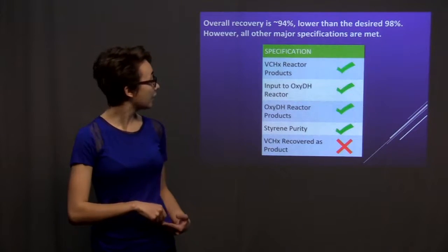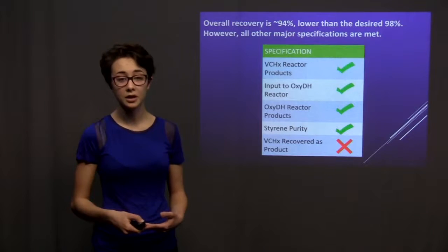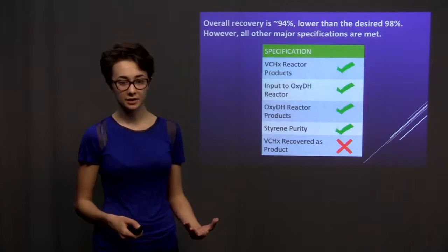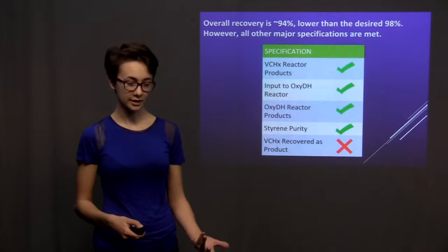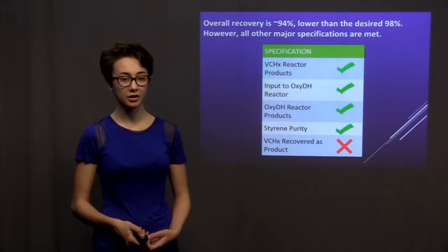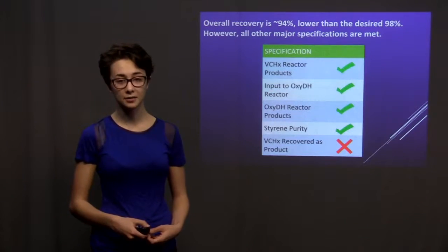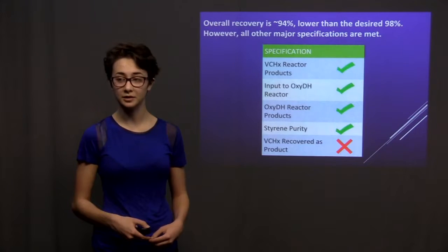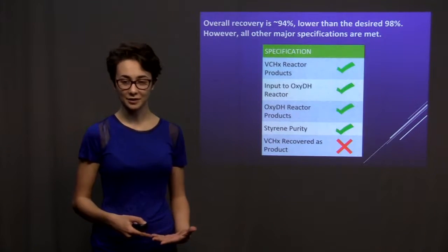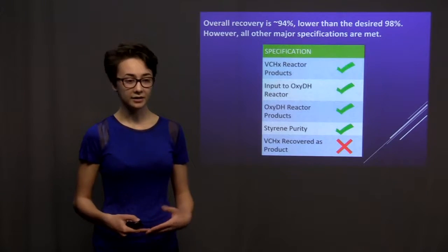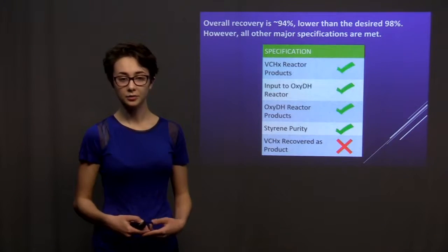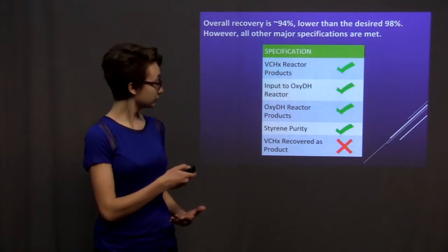The products coming out of our second reactor are also within the pilot plant data, and therefore our kinetics function as expected, and our styrene purity was over 99.8%, at 99.9%, so that is a sellable product.